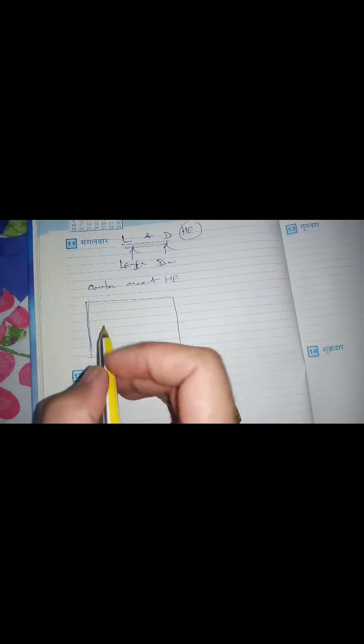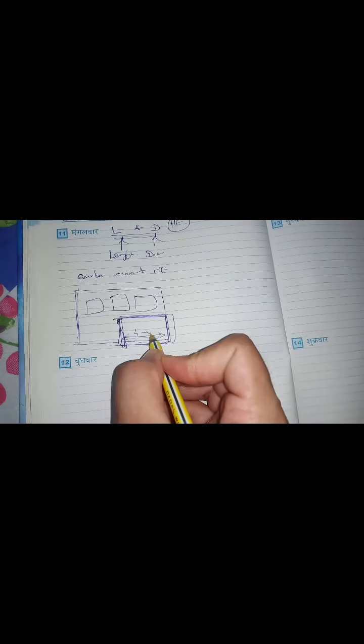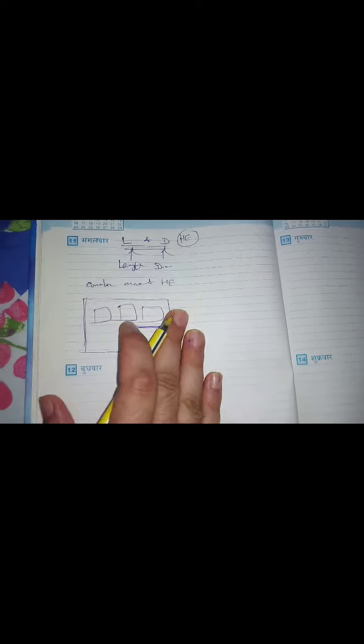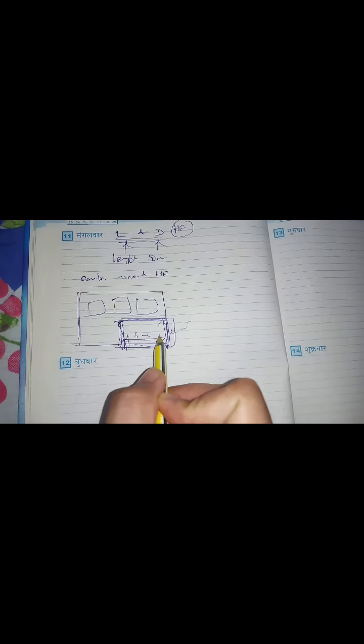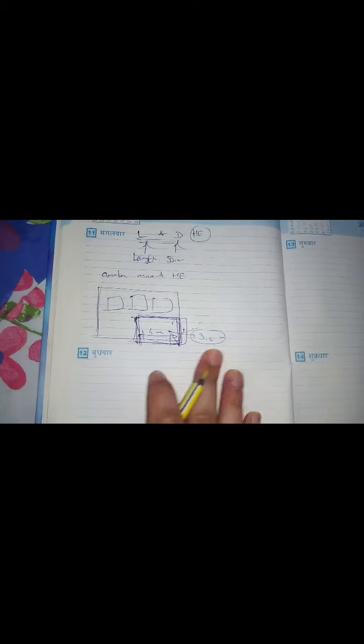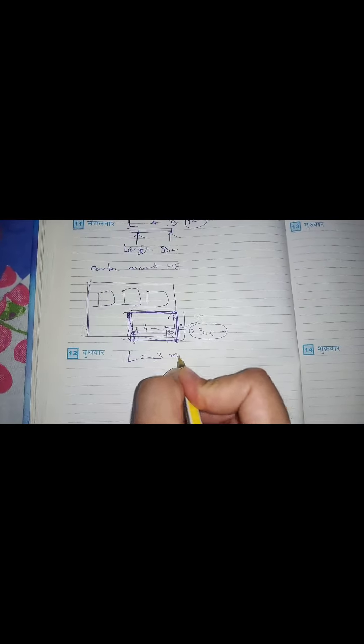Like if your plant has one reactor, one vessel, another vessel, and only this much area is available to locate any equipment, like 4 meter by 2 meter, then your heat exchanger length should not go beyond, let's say, 3.5 meter, because there will be some utility lines. So tell your fabricator, I need length 3 meter and this diameter.